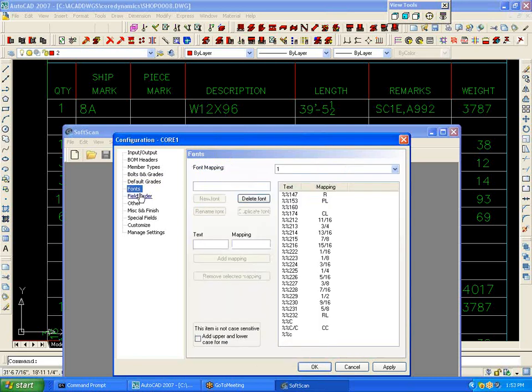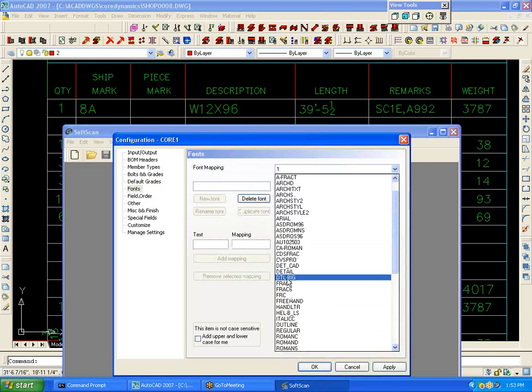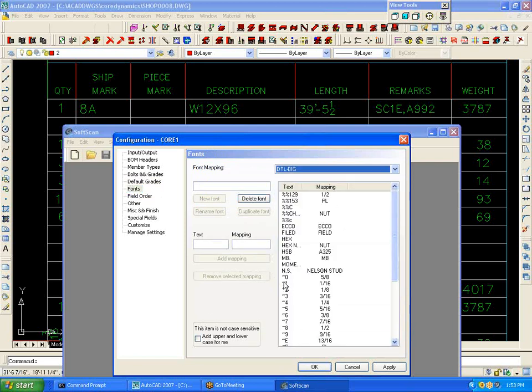Okay, now in AutoCAD drawings, it's very typical for detailers to use fonts. I'm using a font called Detail Big. When I write the dimension 39 5 1/2, I don't type 1/2 to get that stacked fraction. What I do is type 5tilde8. In my particular font, it knows that tilde8 is a stacked fraction 1/2.